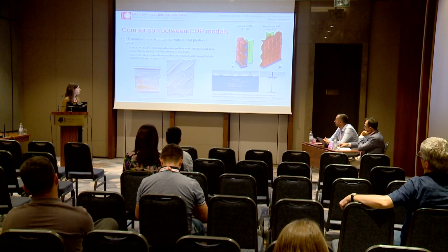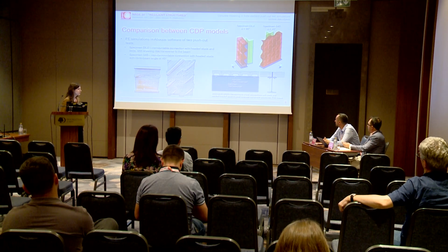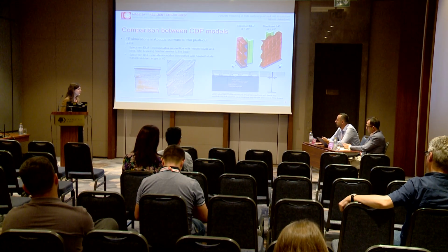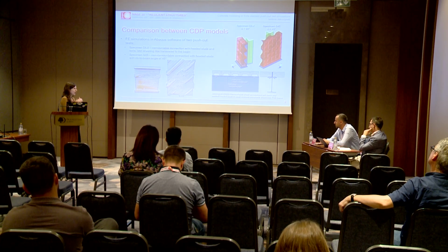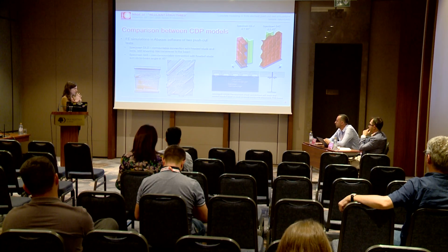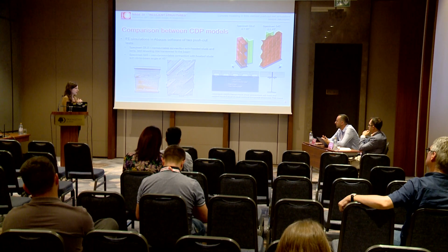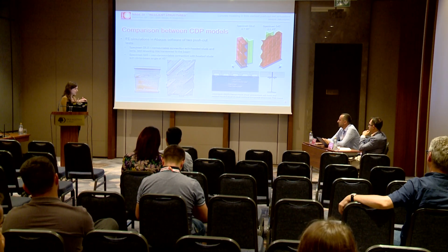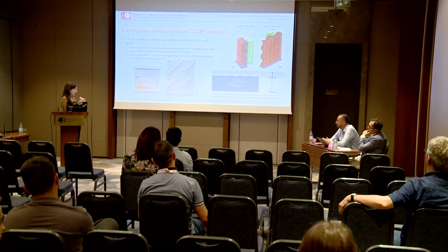And what type of contact did you use between shear studs and concrete elements? Is it bonded contact or? No, I defined the friction and also the hard contact in the normal direction. So there is no separation between the two materials, between the studs and the concrete? Yes, no, separation did not occur.